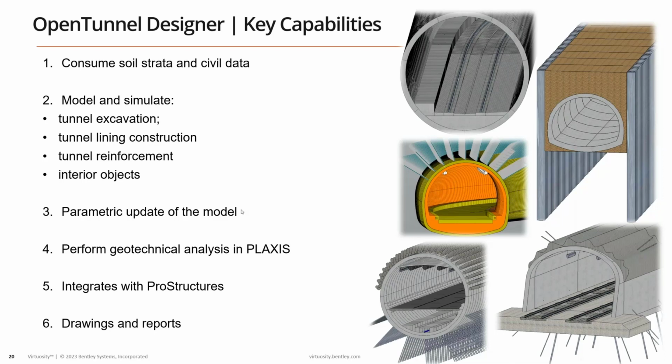At the same time, OpenTunnel has the capability to parametrically update the 3D solid. This is something that the user needs to take into consideration when creating the tunnel template. If the user adds constraints to the geometry that defines the tunnel, then later in the design it will be very easy to just change a value for a given constraint, and the 3D model will update, and after that, all the drawings and reports will be updated automatically.